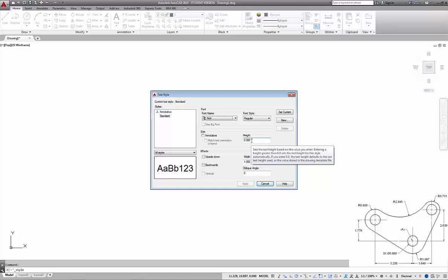So you can choose the height. If you specify a height here, you don't have that control. It sets up the height automatically for you. And it's a good rule of thumb just to leave your height variable and then control that directly at the point of input.